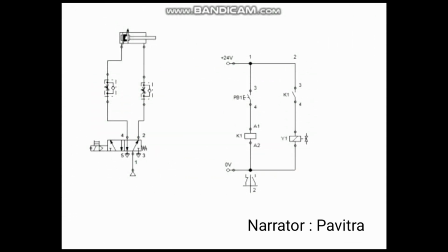Now I'm going to explain about figure 4.1, sustain output. We were requested to construct the pneumatic and electro-pneumatic circuit. Figure 4.1 refers to circuit control for sustain output using push button. We used a single cylinder and a 5/2-way valve. When the push button is pressed, the air is pushed through the 5/2-way valve into the single cylinder. Therefore, it is known as normally closed.